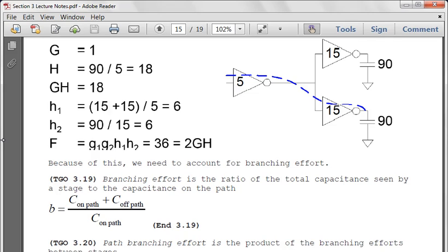So the critical path in our adder is our carryout. But each cell along the path is also driving your sum outputs. Now the sum outputs, if you recall from your data path design, can go back to your registers to be stored, or can go to data memory because we use the summation for load word and store word operations to go to memory. So now you have to worry about driving that particular bus to the output. So that's what we're understanding with this concept of branching effort, this path branching effort that we're going to be going over in a second.